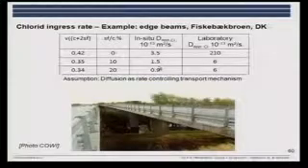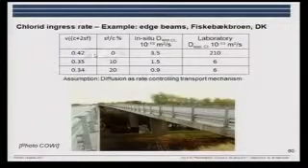We fill all the porosity with water, whereas in situ, the samples may not be fully saturated. And it would be the coarsest porosity which we would saturate on the lab samples, and we have much more coarse porosity in the sample where we don't have silica fume and where we have a higher water cement ratio. So that could be an explanation.